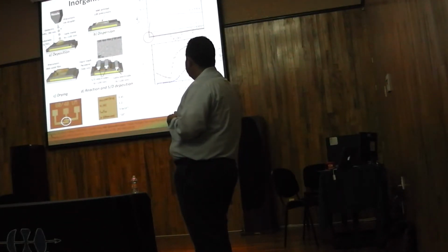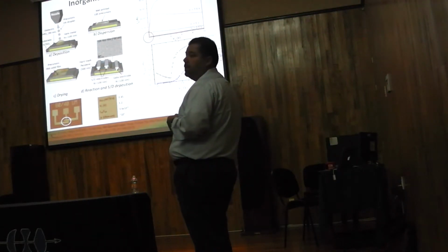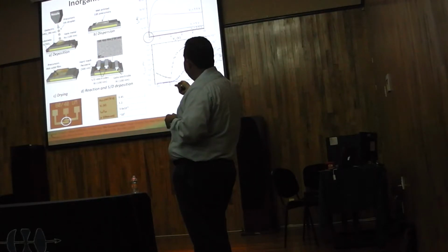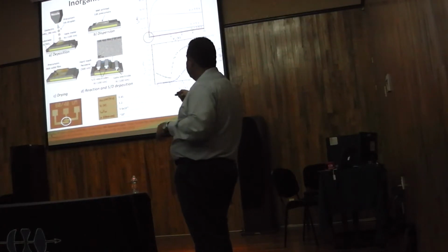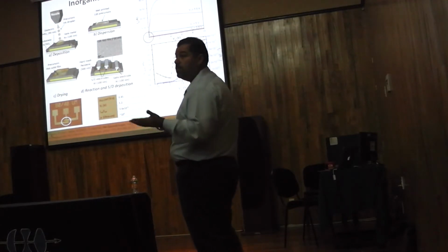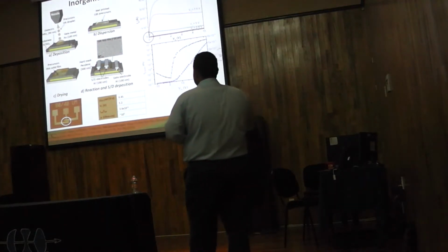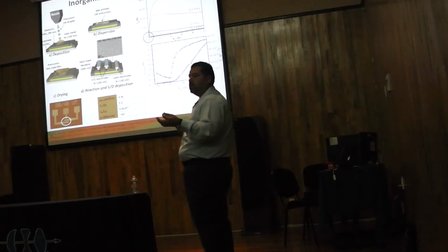We also do typical inkjet printing, right? In this case, what we have is we print, for instance, the sulfur, and then we print the cadmium, and then sulfur and cadmium, and in that way we can also generate transistors. Again, not the best looking transistor, but at least we demonstrated that these devices work with inkjet process.